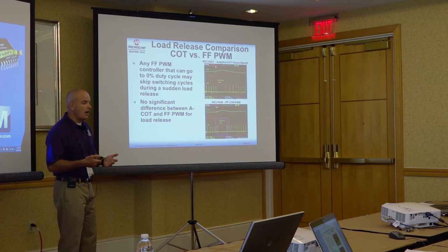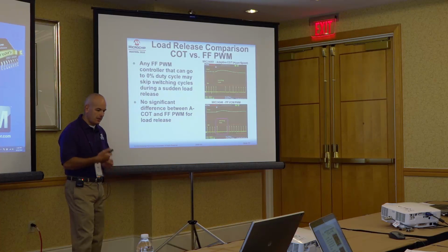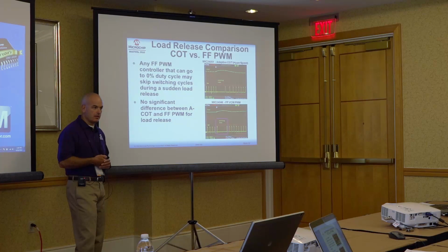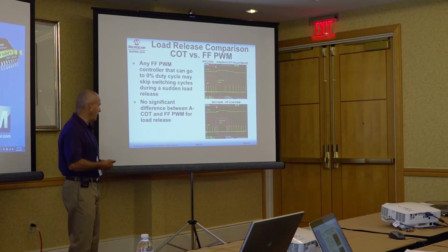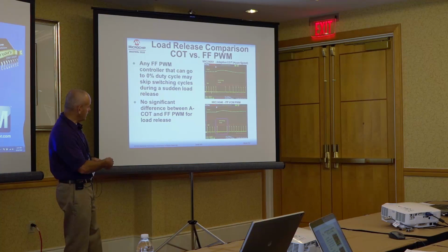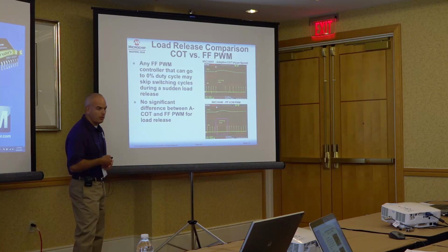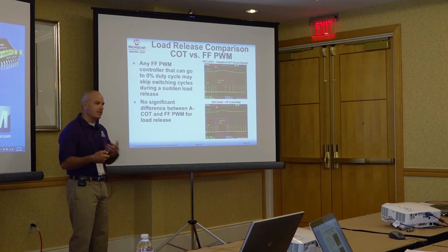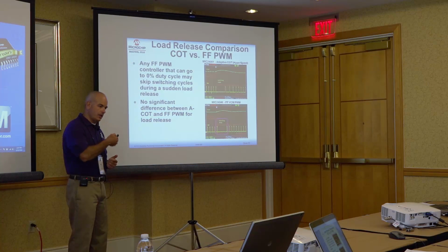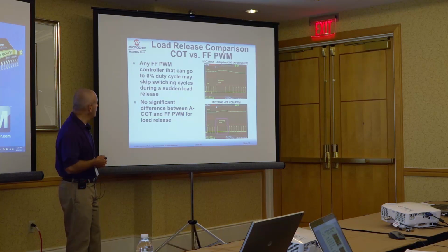So when it comes to aggressive requirements with respect to load transient, and we are pushing the bandwidth of our fixed frequency controller, there is no real difference in behavior of the instantaneous switching frequency during load release.